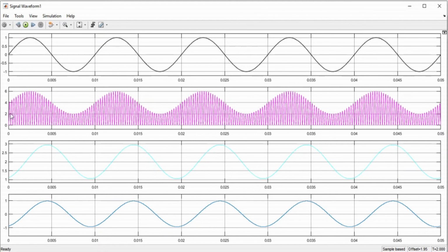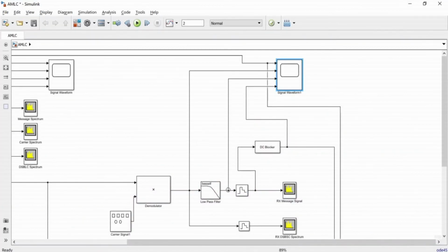If we filter out the high frequency, we have a signal which is basically oscillating between +1 and +3. So we have a signal with a DC offset. You can observe that the envelope is almost the same shape as the message signal, but the output of the filter is a little bit different. That is, this peak has a time delay to this point; it is now shifted over here. Again, this is the characteristic of the filter that we use, and that filter basically introduces a delay. Anyways, we have a signal at the output of this filter